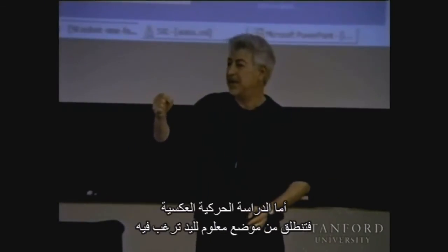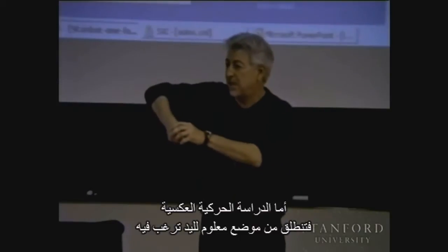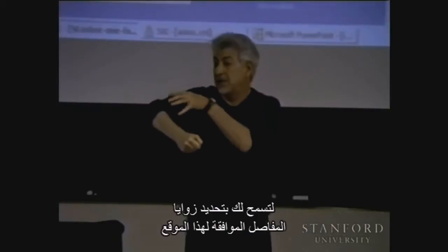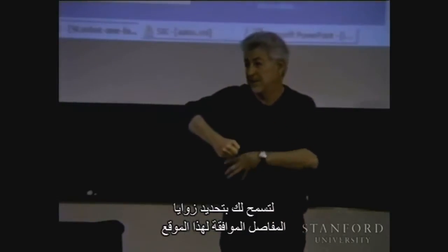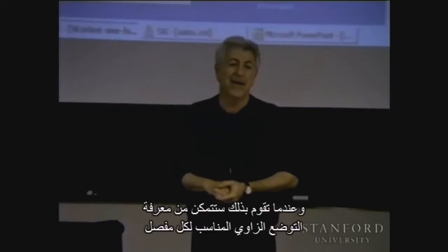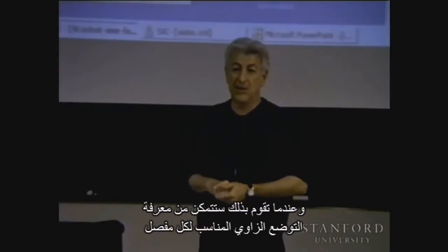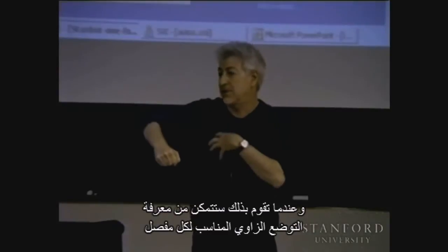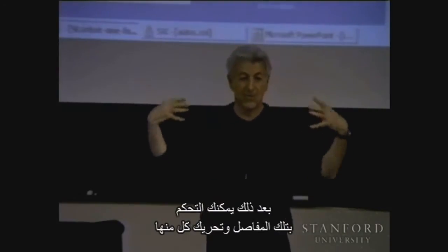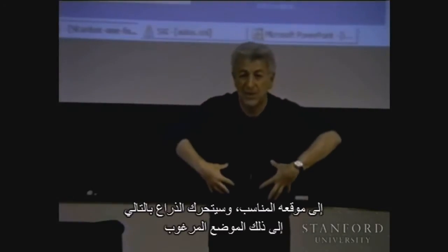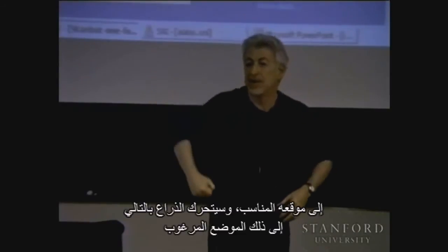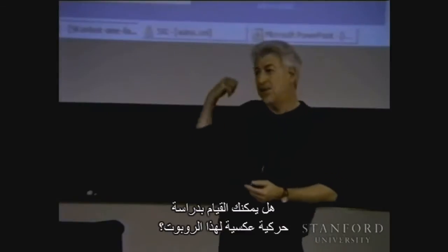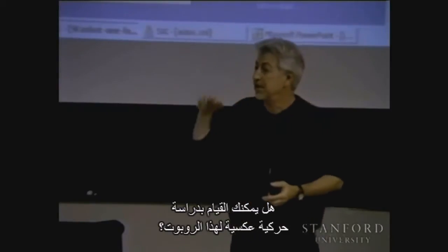The inverse kinematics gives you, given a position for the hand that you desire, the joint angles that achieve it. And if you do that, then you know your goal position angle for each of the joints. Then you can control these joints to move to the appropriate joint positions, and the arm will move to that configuration.